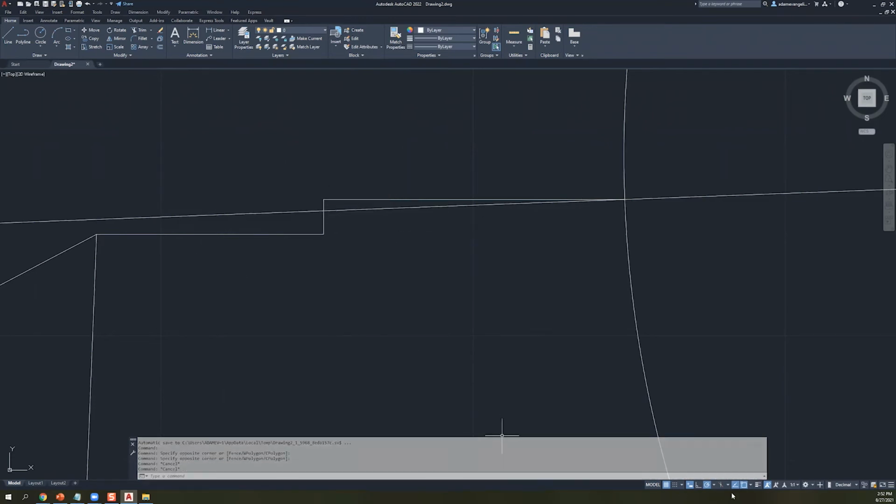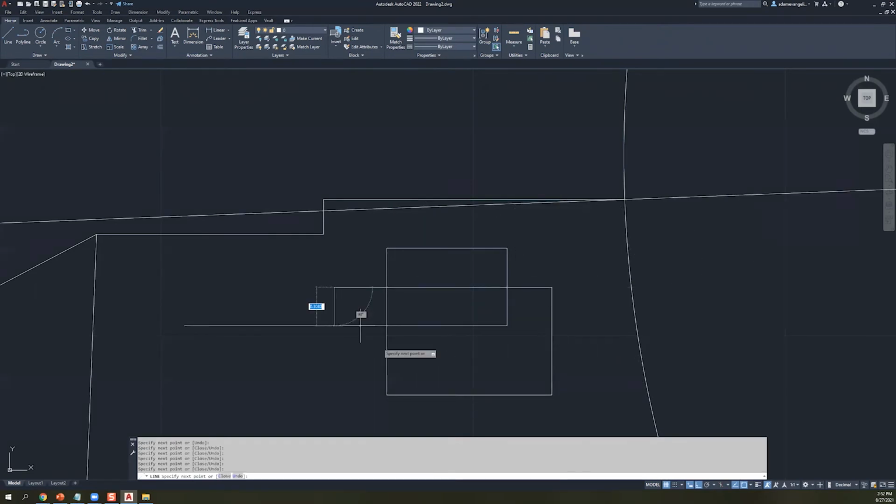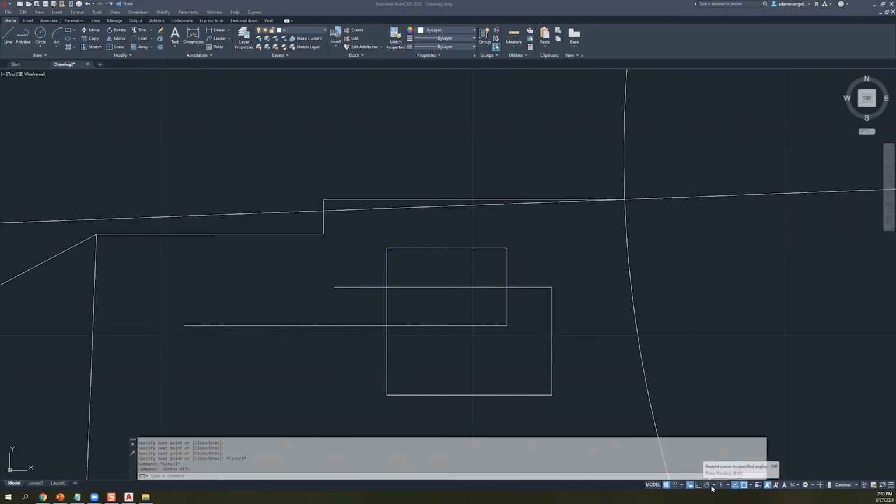In a similar vein, you have other snap stuff like ortho mode, which was a common one that showed up a lot, where it'll restrict you to 90-degree bends. So kind of the same idea, but another way to get to that kind of thing. So you could turn off ortho mode. I don't use it that often. It's good to be aware of the different radial settings as well. There's radial angle snaps as well. And where are those? I think that's this one over here.